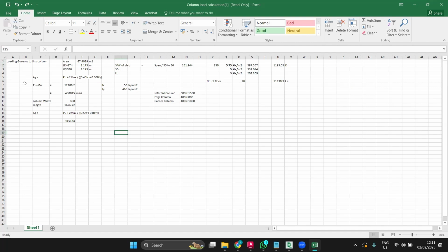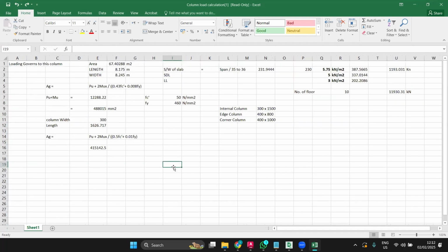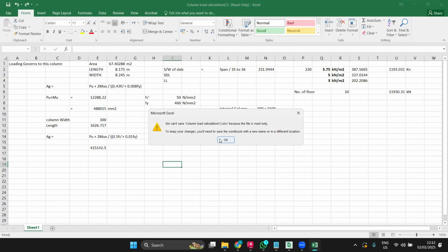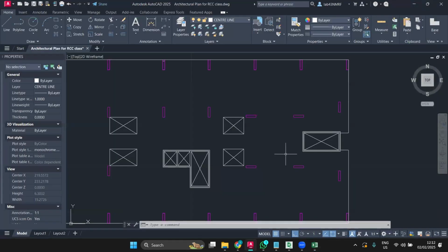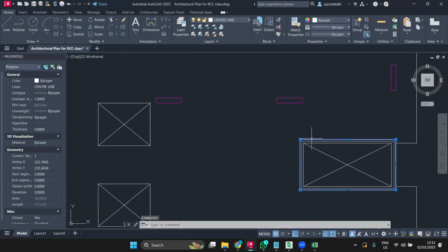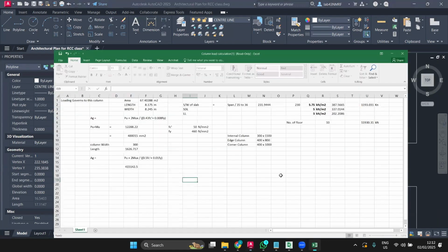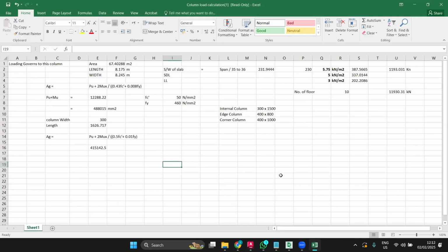But try to keep in mind that if it is 8th floor, do not reduce your wall thickness to less than 300 millimeters. Because there is some extent to which you cannot increase the columns. Then the wall will help you make it safe for the serviceability criteria. To make it safe for the serviceability criteria, you need stiffness. The stiffness you cannot increase by increasing the columns because the column is a frame element. So you need a huge moment of inertia that you can get only in the walls.